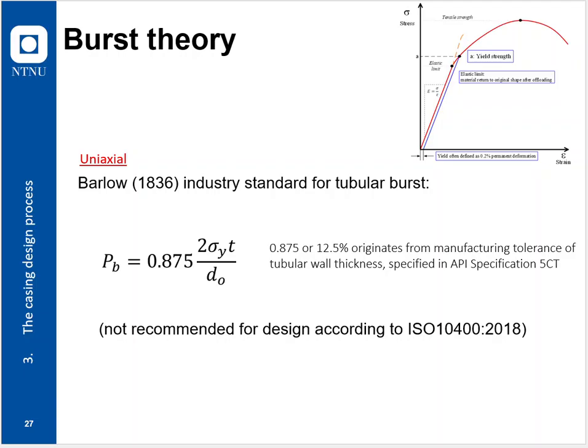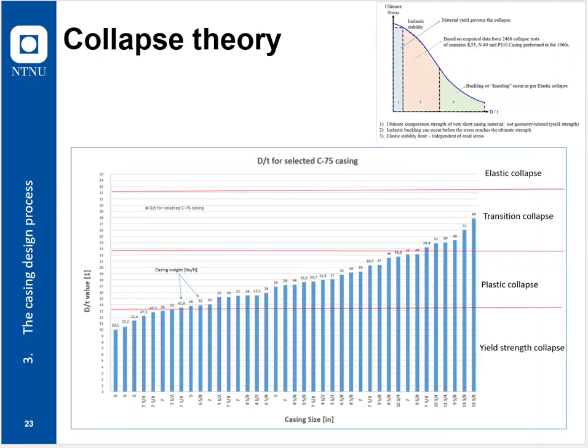The industry is using this formula, and it says that we are tying it to yield, 0.2% deformation, and it all becomes a little bit difficult, at least for me. When you're using this formula, it is very old style, with figures tied to what is not so very often occurring anymore, wall thickness 12.5%, and a calculation valid for, just to be quick, 70% of these pipes.